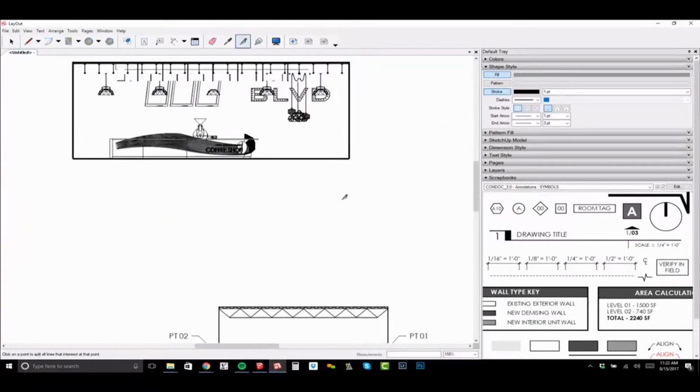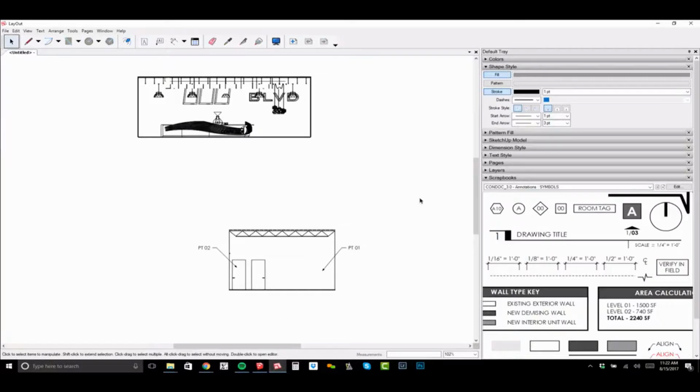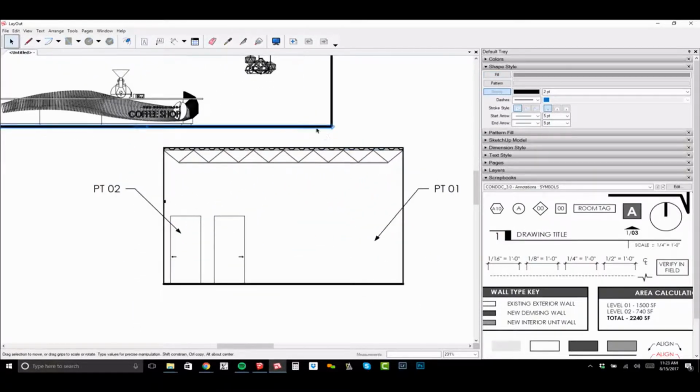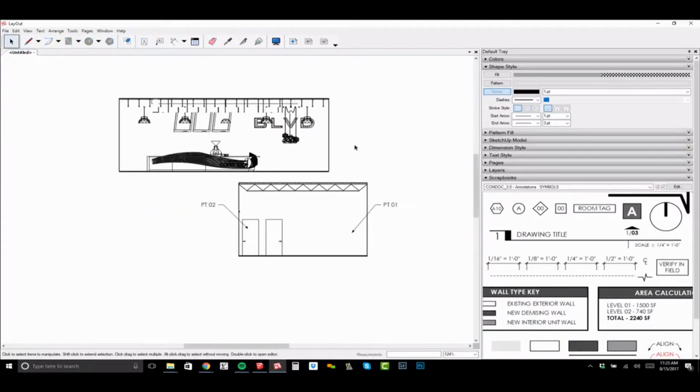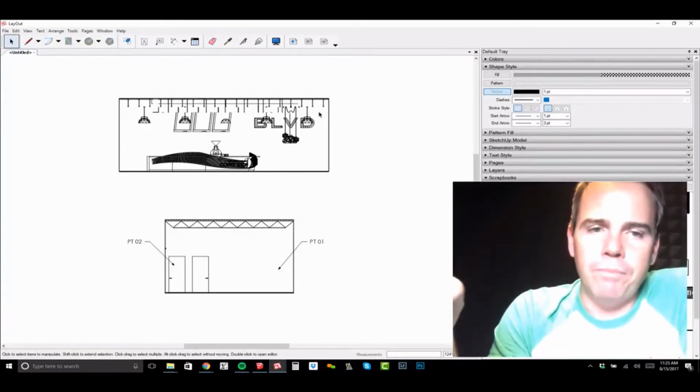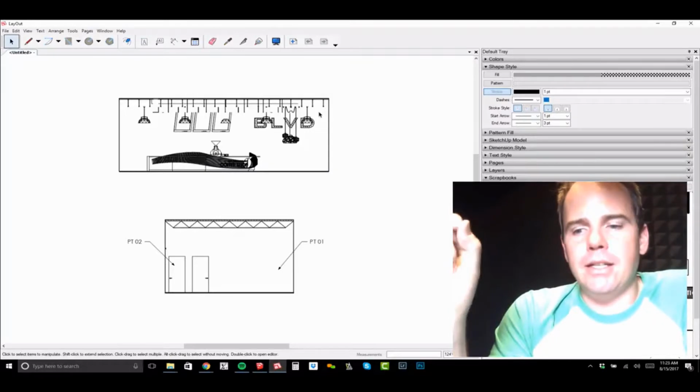And then again, instead of always working inside of this shape style, sometimes it's easier to select this edge and tap S, and then soak up the properties of this edge. Click this edge, tap S, and soak up the properties of that edge. So now they have the exact same styles on them. So that's how we create some interior elevations using ConDoc, the section tool, and then clipping masks in Layout.